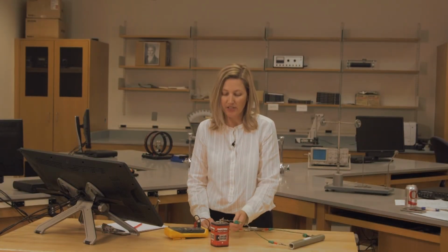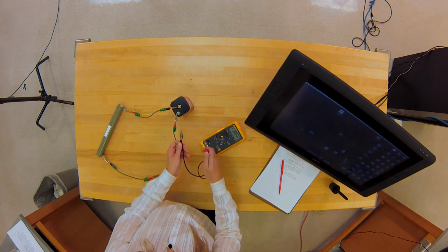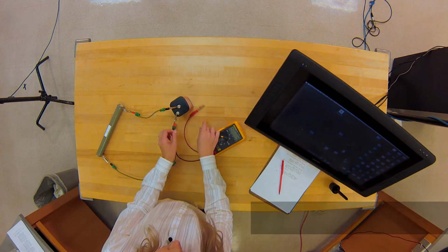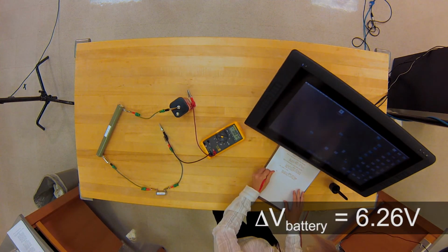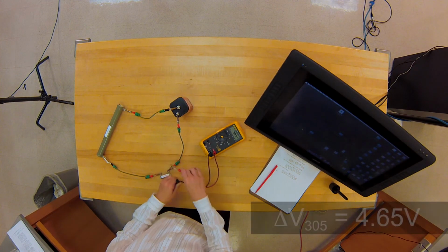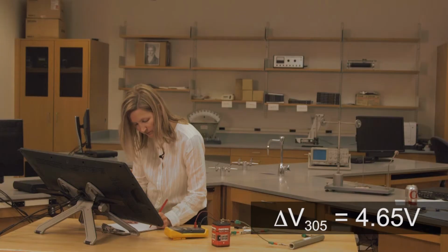Let's check Kirchhoff's loop rule with our electrical circuit. We'll use the same series circuit we just used a moment ago. So let's measure the potential difference across the components of our series circuit. First, I'll measure the potential difference across the battery. 6.26 volts. Now let's measure the potential difference across the 305 ohm resistor. 4.65 volts.